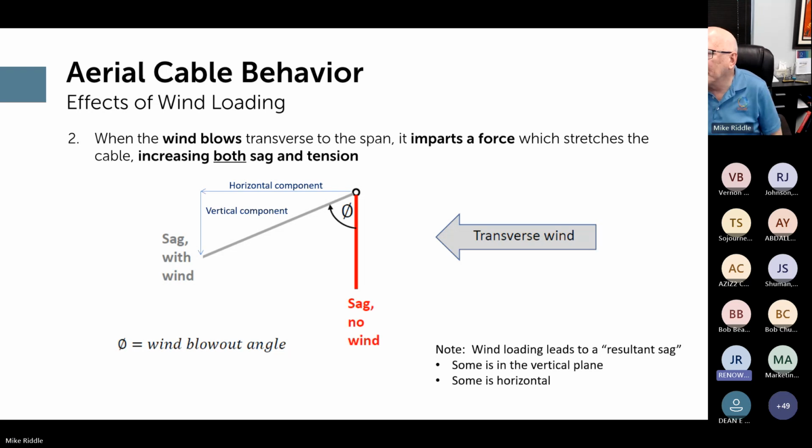Mike, could I make another observation, especially about field installation of conductors? Absolutely. If the sag of a conductor is being installed using a survey instrument, like a total station or even an old engineer's level, the conductor can be brought to its initial sag very precisely, well within the diameter of the conductor, because that instrument is very precise.